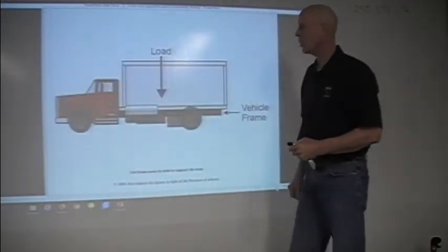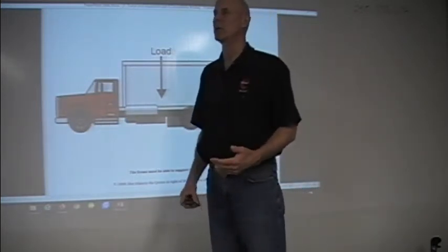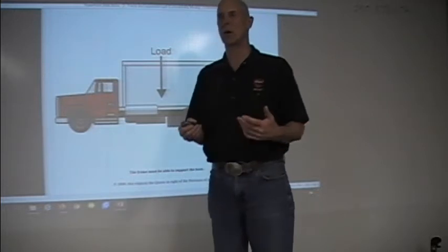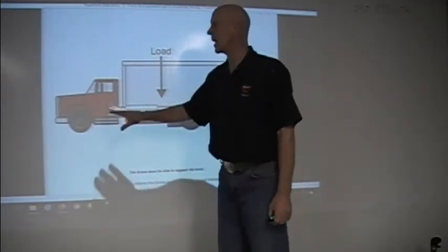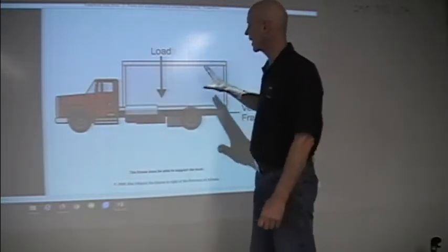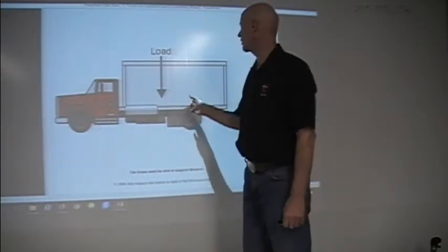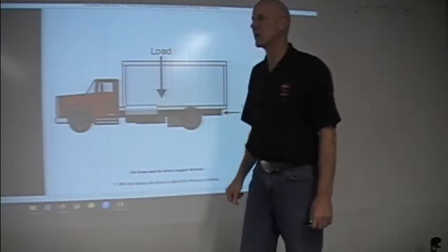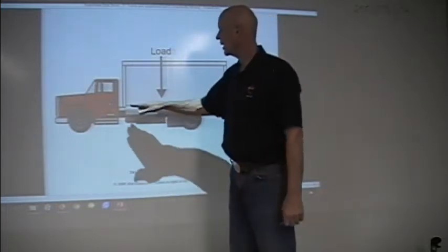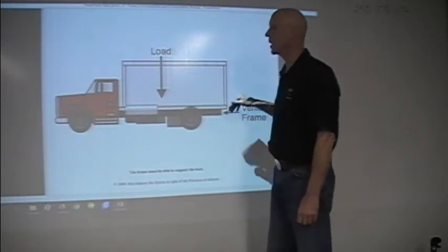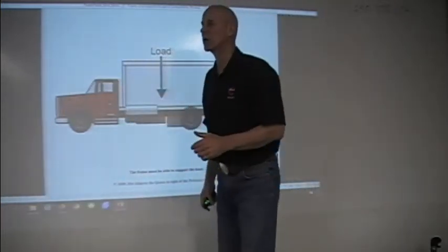So number one is, again, I can't just take any truck and use it for any application I want, because if it wasn't designed for that, the frame may not be strong enough for that. So for instance, if I have a single axle, I've got a day box on the back, where's my center of load? So if my center of load is, let's just say 5 feet in front of the rear axle, is that frame strong enough? Well, there's different things that they do. Underneath the box they may run a full bar to help spread that load out over a longer distance.